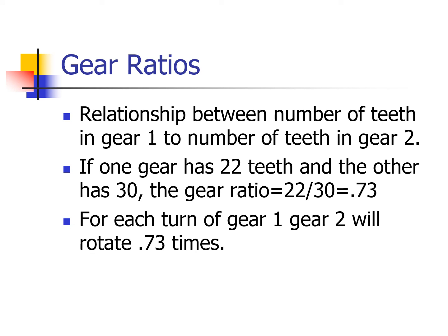So you will go to a smaller gear in the front of your bicycle and a larger gear in the back, and you'll have a less than 1 gear ratio where you'll be pedaling faster than the rear wheel is turning. And then when you get to the top of the hill and you start going down, you will switch to a bigger gear in the front and a smaller gear in the back, and that will end up giving you a ratio where you're decreasing your torque, but you're increasing your speed.